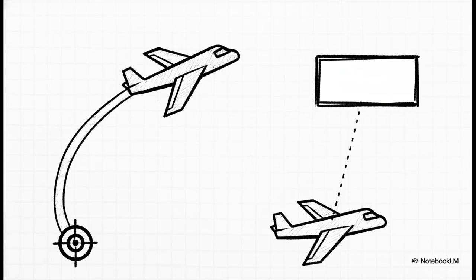To help you anticipate exactly what your screens are going to do, lock this visual link into your memory for effortless recall. Above, pass it. Below, show it. If you're above the altitude, expect the FMS to sequence past it. If you're below, expect the screen to show the target altitude while keeping the identifier blank until it's active.